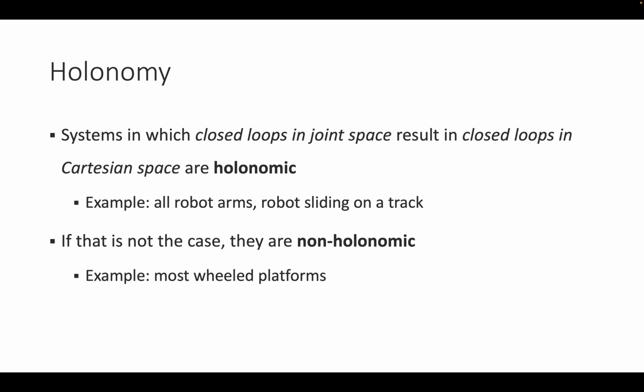A unicycle is not holonomic because it can turn on the spot, it can move back and forth, and it can end up anywhere in the space depending on the sequence of actions that it takes. A unicycle on a rope instead is holonomic. It can only go back and forth on the rope, and thereby the wheel position always determines where the robot is.